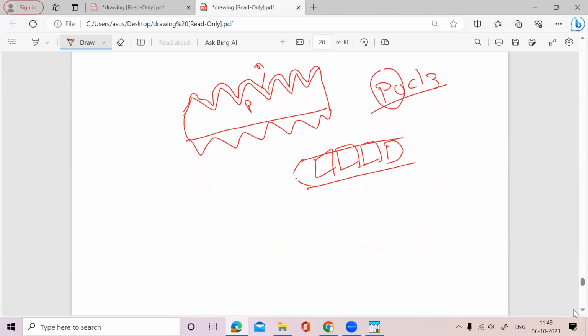I have to give some gases. Actually, we have to use oxygen, nitrogen, and also POCl3. But this oxygen and nitrogen are treated as carrier gases. And I have to give POCl3 into this wafer.